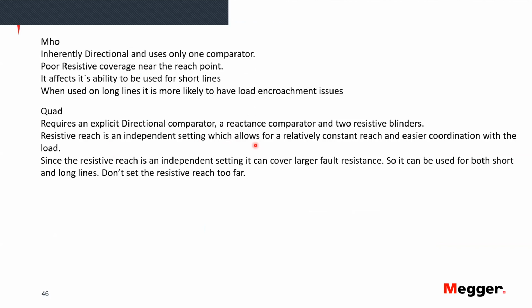Remember, the load comes on that side, and I can make it close to but not into the load. And the fact that the resistive reach is independent means it can cover large fault resistance, so it can be used for both short and long lines. But just remember, don't set the resistive reach too far.